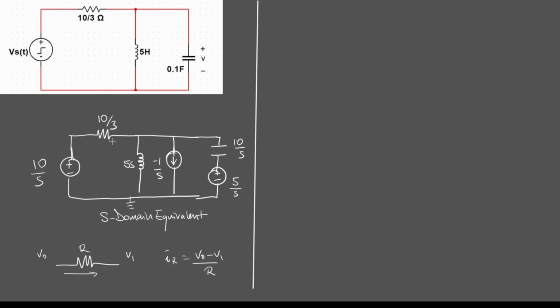Okay, first of all, set up our currents. We'll call this I1 entering the node, I2 leaving the node. So I1, I2. We already have the direction is down. Direction is always going to be down. Our value was 1 over S, so we're going to leave it as that. I3 is also leaving the node. And I4 coming from these two guys is entering the node. Simple and straight KCL tells us that I1 plus I4 is equal to I2 plus I3. Everything we're going to do is going to be based off of this.